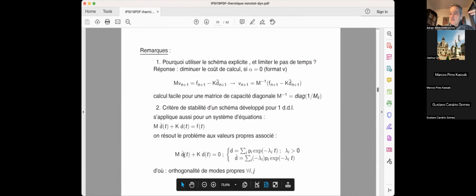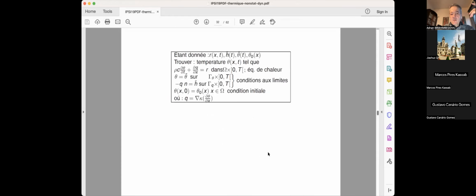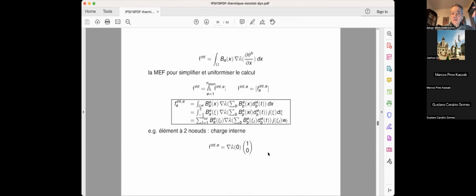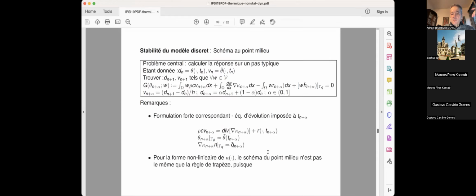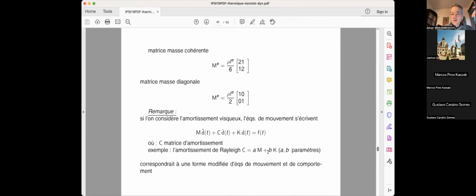But this time, given that this is a second derivative, instead of lambda you'll have something like omega squared, and then it could be exponential of i omega t, which could be cosine omega t plus i sine omega t. So both the modes and the values of these things will be different. So this is your modal superposition analysis. If you did a simple course on linear dynamics, I'm sure you have been through this already.